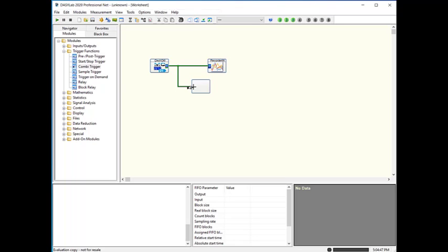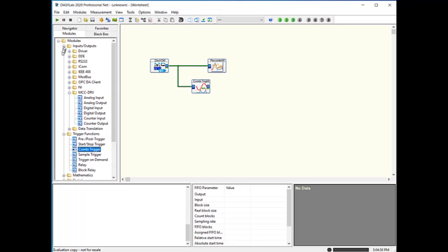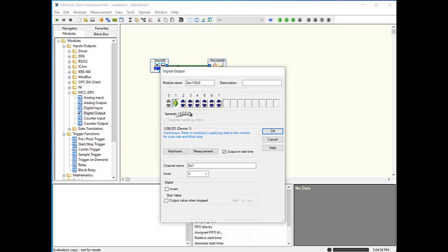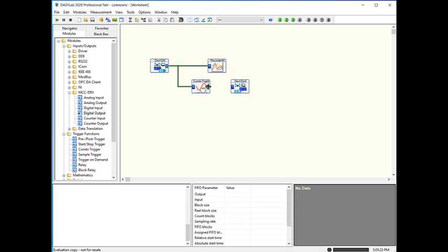This is going to control a digital output. So back to the Input-Output group, create the digital output, and select the same port. And now you see channel 0 is already in use. It's in use by the digital input. I have wired my device to use channel 7, so I'm double-clicking on 7 to enable it, and then I will double right-click on channel 1 to disable it. This will update at the rate coming into the module. So it's going to use the rate in effect from the digital input at 10 samples per second.